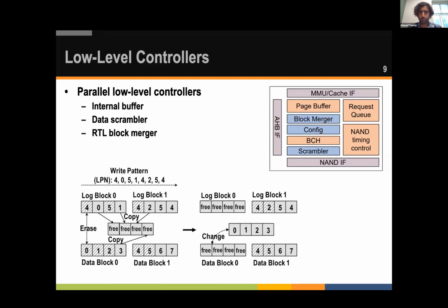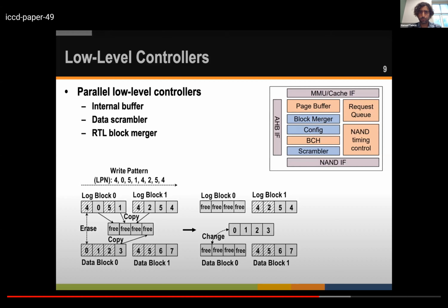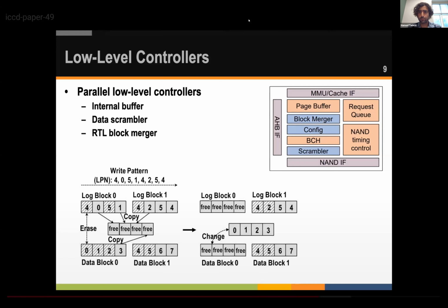currently being returned to. This scheme is very efficient for wear leveling, but it requires expensive full merge operations, as shown in the bottom figure, where many pages are moved and copied. To avoid CPU processing and passing around large pages through the channel multiplexer demultiplexer, we perform in hardware this expensive merge operation during garbage collection inside each low-level controller.